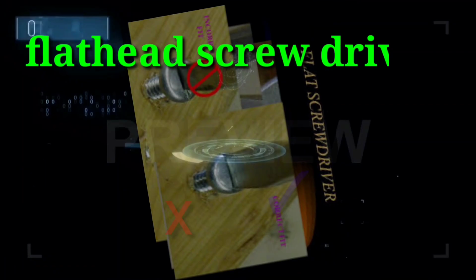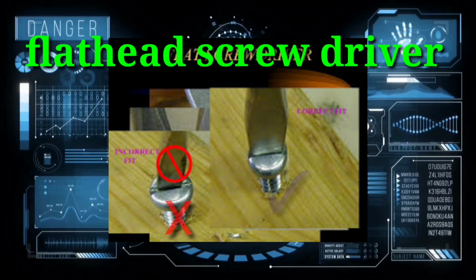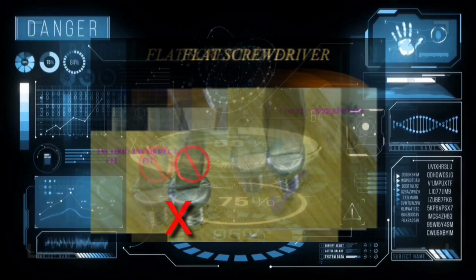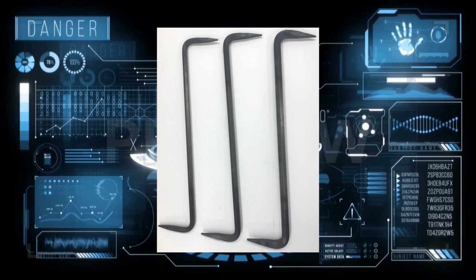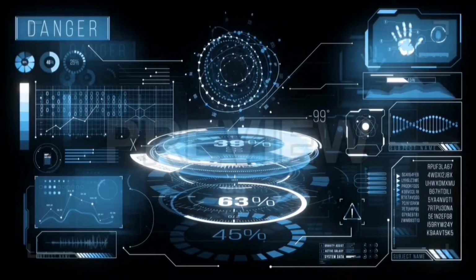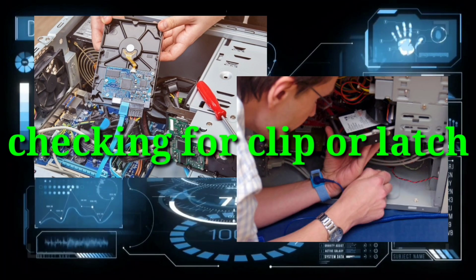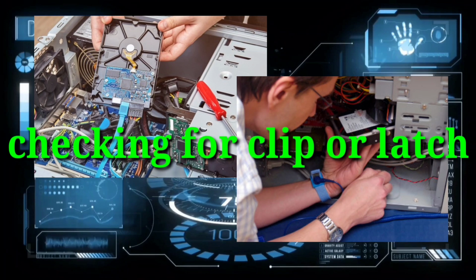Flathead screwdriver. Don't use a flathead screwdriver to remove a Phillips head screw. Never use a screwdriver as a wrecking bar. If you can't remove a component, check to determine if there's a clip or latch securing the component in position.